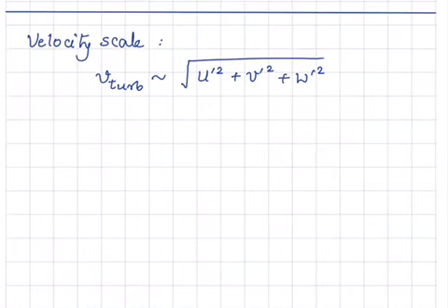And because everything is varying in time and fluctuating, we will take a bar of it so that we get a reasonable thing to handle. So this is a way of defining one single velocity fluctuation, or a characteristic velocity, instead of three different directions: only one number which represents the three directions together as the velocity fluctuation at a given point. And this turns out to be the square root of twice k, as per the definition of turbulent kinetic energy we have defined. So if you know turbulent kinetic energy, you can actually get the velocity scale, the characteristic velocity at a given point.